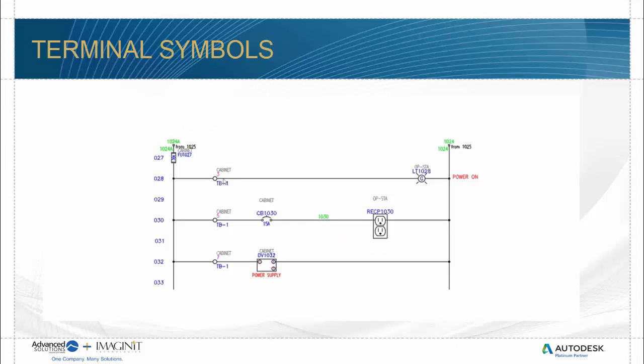So as we place them, this is what they look like. So here is really what we're talking about. And so instead of having a mass of these type of things in there, you may have a list or a stack of them, as I call it, which is what we've got here, all right? And these are different terminal block connections that we're using as a terminal strip. And the terminal strip indicator is this down here at the bottom. It tells me which terminal strip, what the terminal number is, and what the location of that is.